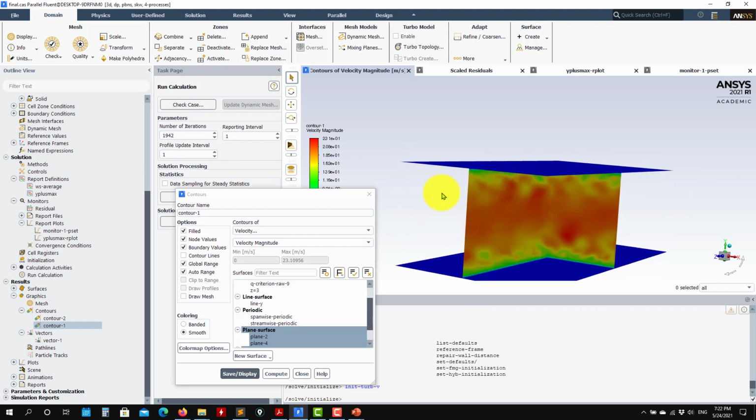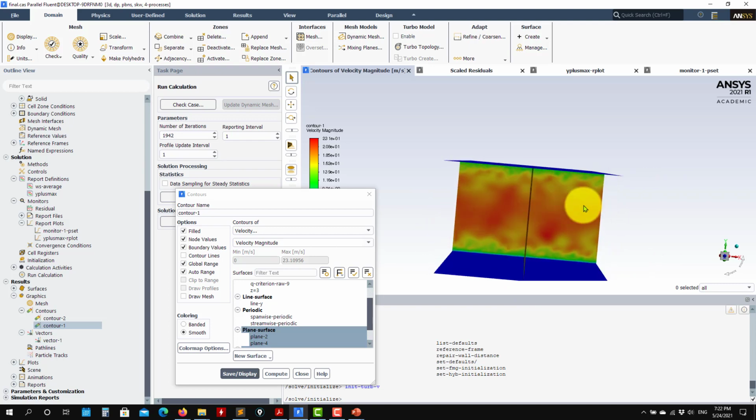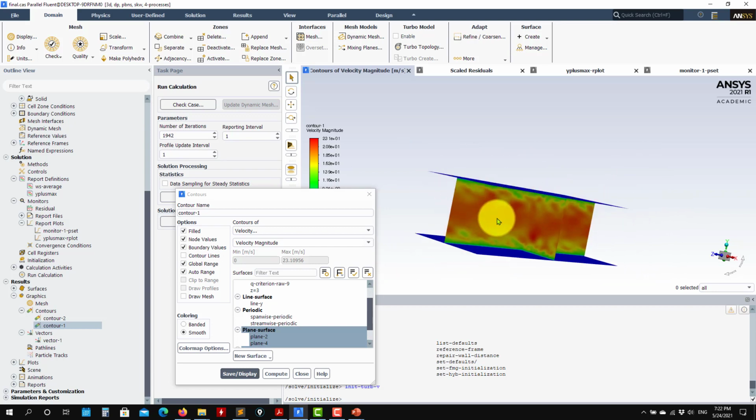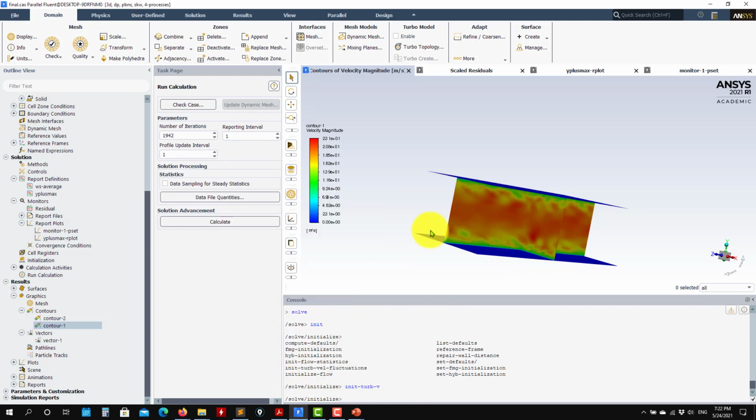Now this is a much better starting point for a scale resolving simulation. If I put this in the RANS, immediately the RANS will smooth all this fluctuation. Same will be for the URANS. The URANS will smooth this. Probably will conserve something, but you are not going to see anything. We're not going to see those streaks there, because everything has been averaged by the model.